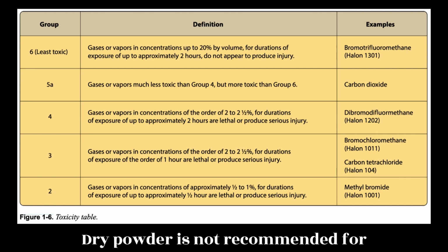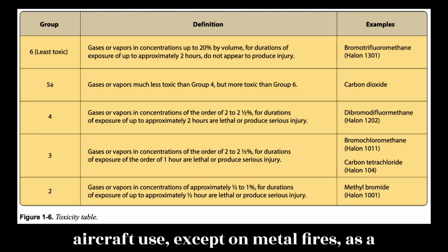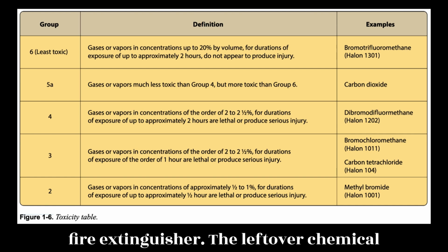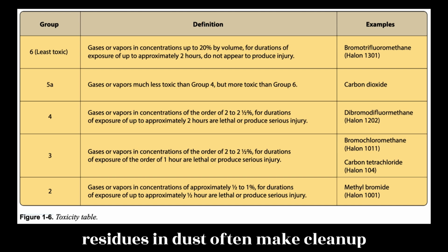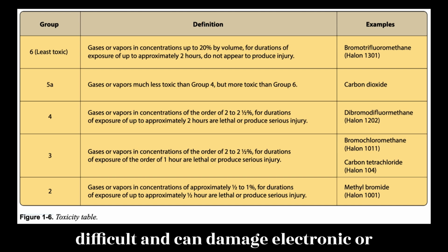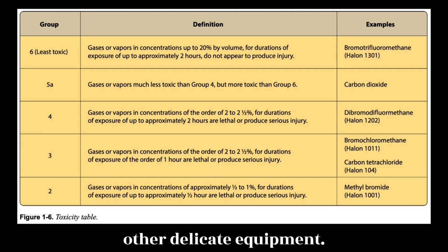Dry powder is not recommended for aircraft use, except on metal fires, as a fire extinguisher. The leftover chemical residues and dust often make cleanup difficult and can damage electronic or other delicate equipment.